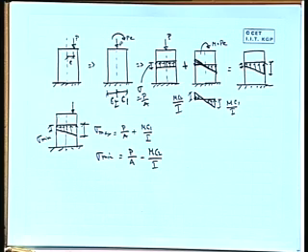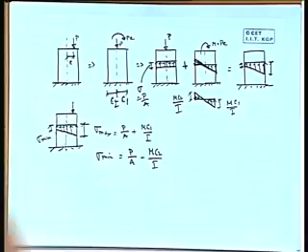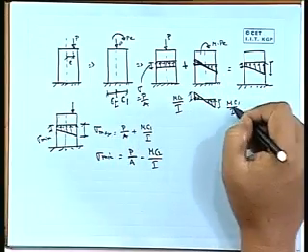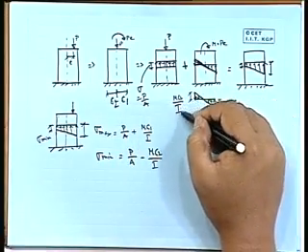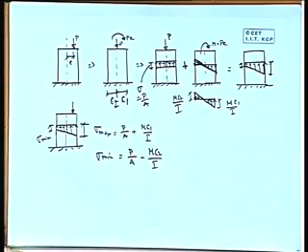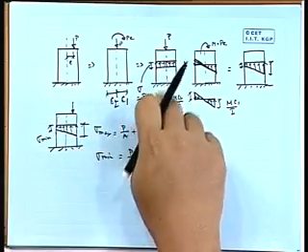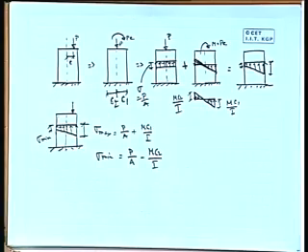Now, here there will be no pressure; some pressure will be there in a negative form, that will be your tensile stress, not a compressive stress. Now, here in bending, MC1 by I and MC2 by I are the bending stresses, maximum one is compressive, another is tensile, and here P by A is the direct compressive stress.